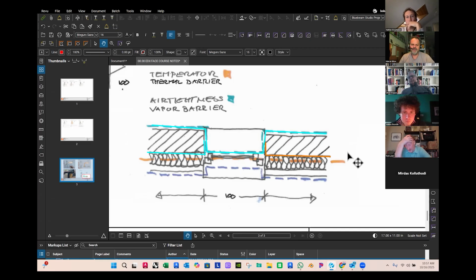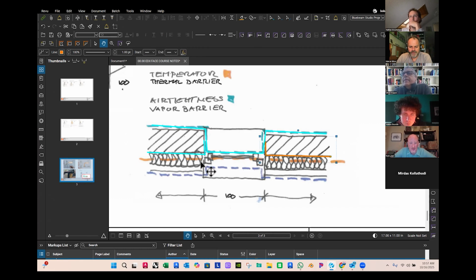Okay. What is your experience, and in which field do you work? We provide ventilated facade solutions for companies, and it's exclusively commercial buildings, hospitals, museums, things like that. So it's all commercial. And so this orange line here, I've been doing this for 12 years, and they call it the AVB layer, the air, vapor, and water barrier, or AVW.